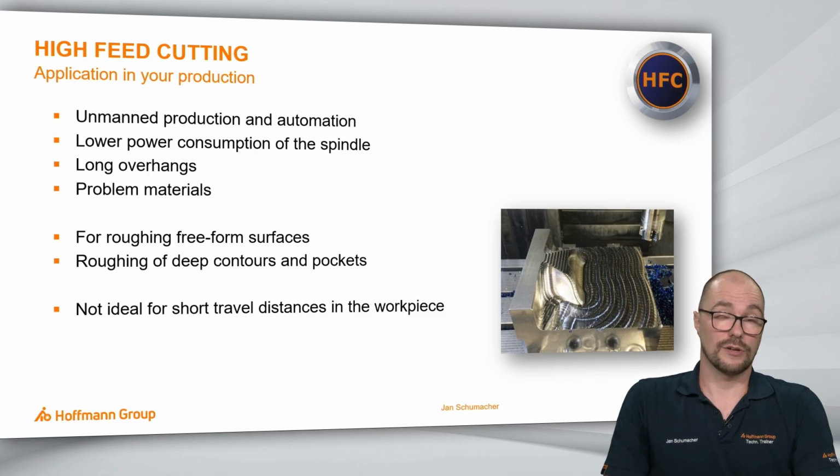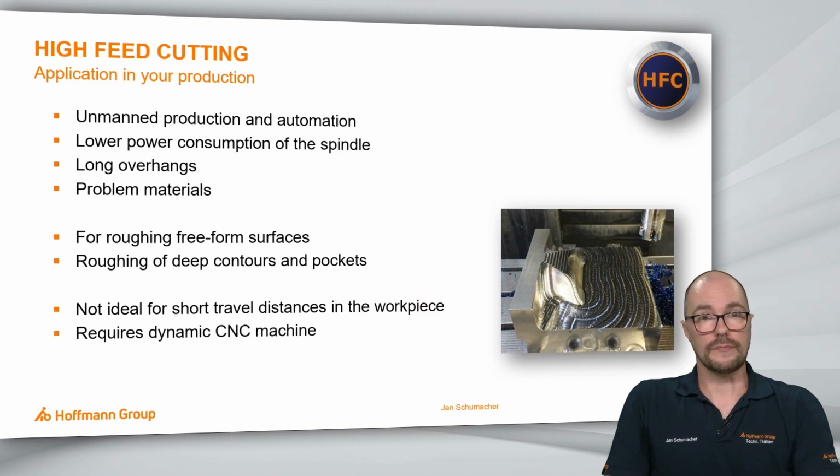Downsides, not to forget to mention: it is not really ideal when you have very short travel distances in your workpiece, because your machine usually cannot accelerate fast enough to generate the necessary feed per tooth. And of course, your machine has to be quite dynamic and rigid.